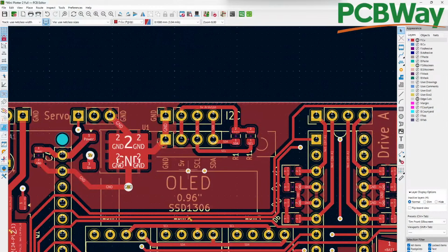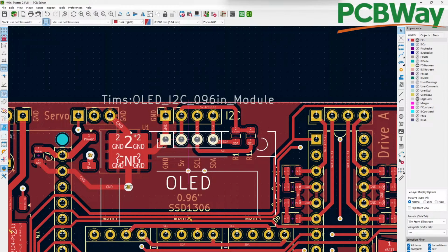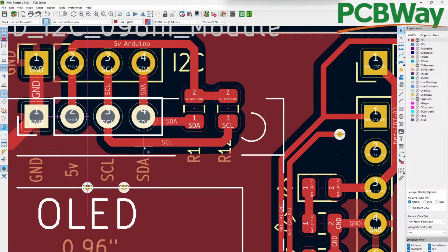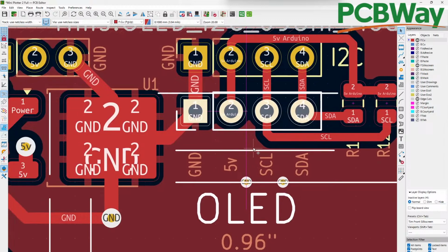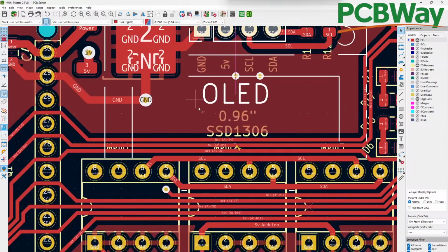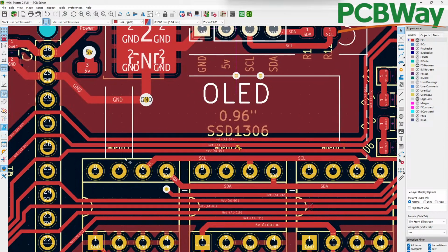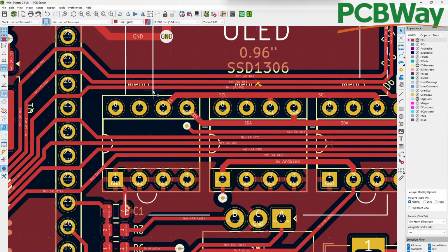I did the same with this OLED. Well, the OLED I made, you see, can you see I've actually edited out some of these lines so that the silk screen doesn't go over the top of these other footprints, and you can see it's going over this component as well, so it has to be excluded from the OLED component. And same again here, I've had to modify the footprint silk screen so that it oh, there's one there, look.